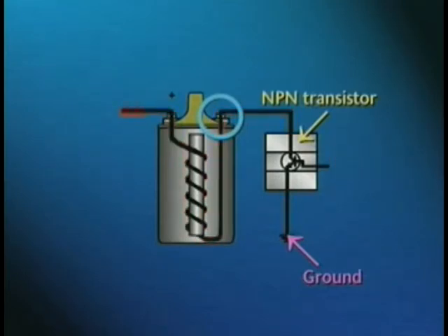The collector is connected to the negative terminal of the coil. When a small amount of current is supplied to the base of the switching transistor, current flows through the transistor and the primary coil windings. When the current flow to the base of the transistor is interrupted, the transistor blocks the flow of current through the emitter and collector, effectively opening the primary circuit.